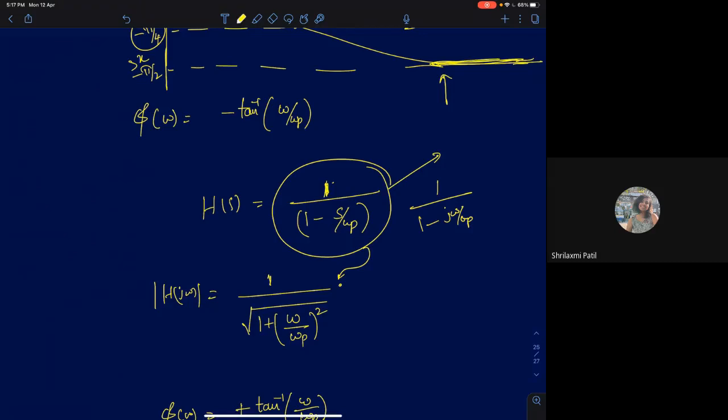As I said in the first step, we look at a system. If you know the transfer function, you can say if it's stable or not. Is this a stable system? If you see the system, is it a stable system? No, right? The poles are in the right half of the s plane. The pole is at s = ωp, yes, if ωp is greater than 0, that is the case. It's a right half plane pole, so the system is indeed unstable.